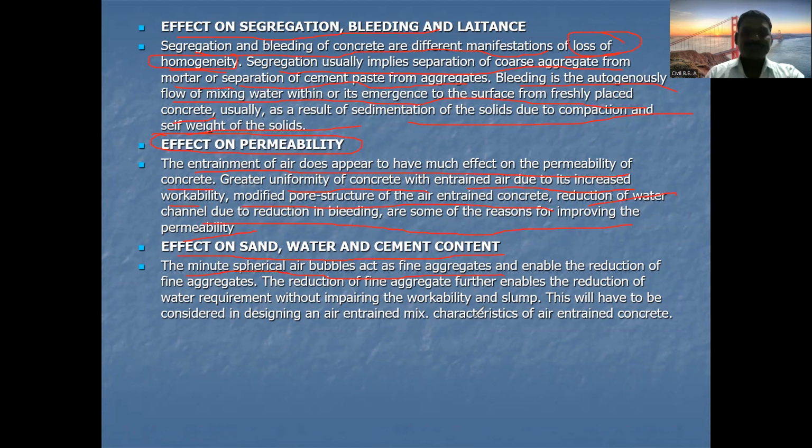So that enables the reduction of the fine aggregate. The reduction of fine aggregate further enables reduction of the water requirement without impairing the workability and slump. We have to consider this when designing the air entraining mix.